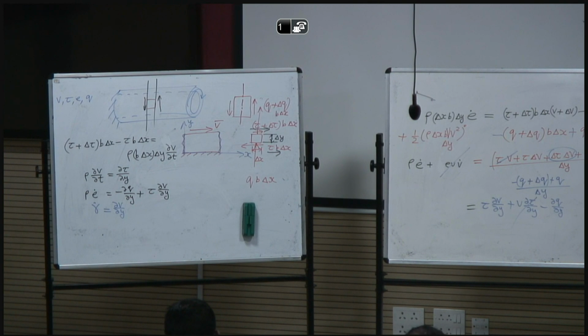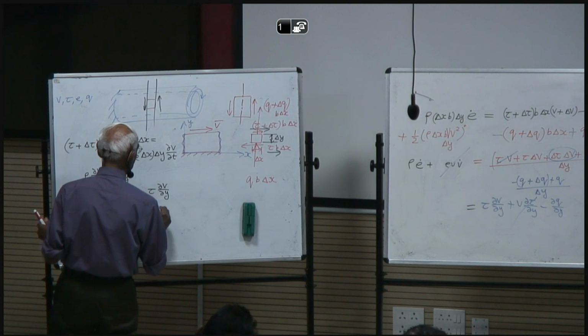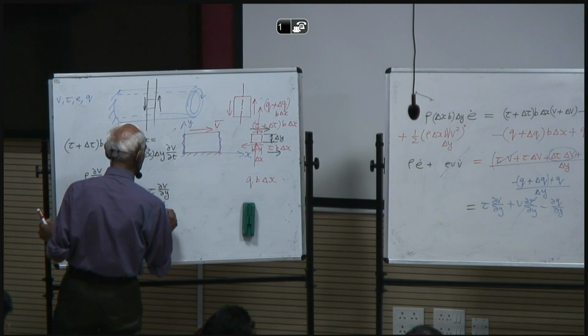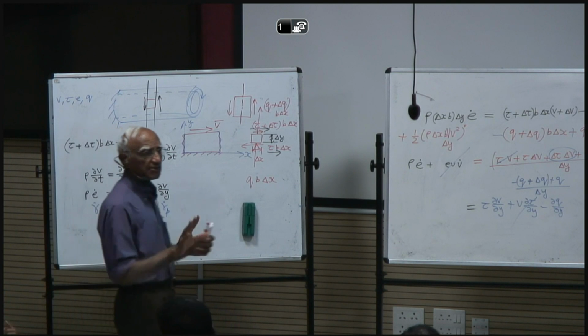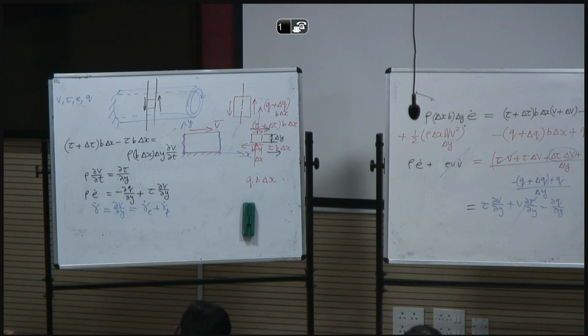In plasticity, we assume that strain rate has additive decomposition, not strain. Unless you are doing a small strain problem, we do not say strain equals elastic strain plus plastic strain, because these are components. But strain rates you can say.